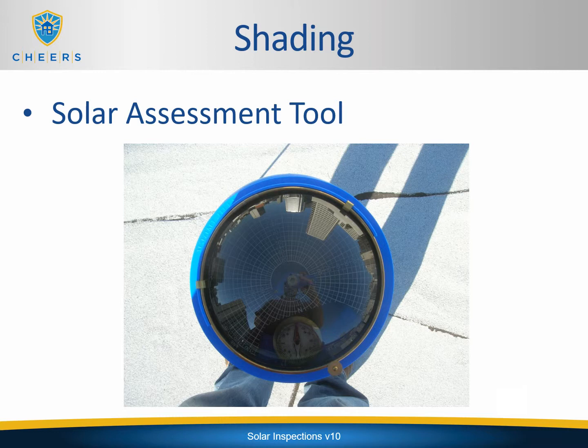You would draw this outline on the paper that is underneath this dome to show which buildings would cast shadows on the structure and at what time. You would then need to use the documentation that comes with the Solar Pathfinder to determine what the shading angles are to determine if it meets the 2-to-1 criteria.